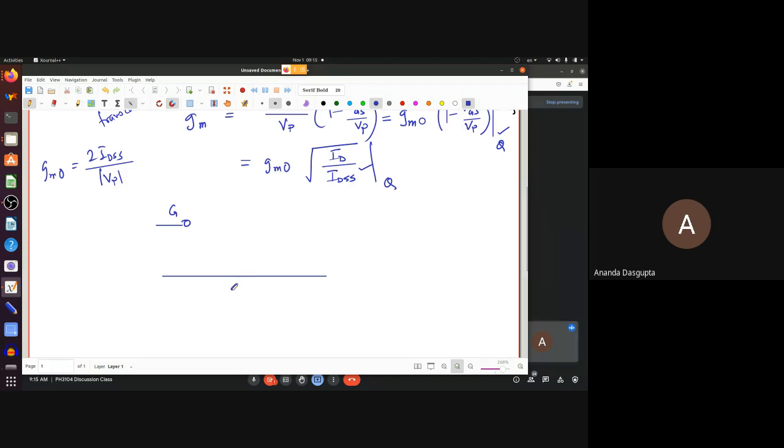You have the source here, down here. So this entire line will be connected to the source. So you want an infinite impedance. How would you model that? By a break in the circuit. Right. Or by connecting nothing here. That's it. So this is how the FET is modeled.